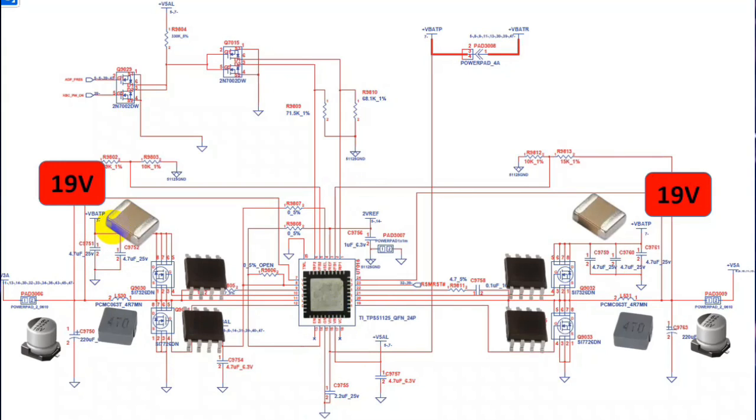Okay, so the same working principle here. So always the components that you should check when you have a failed 3 volt 5 volt circuit are the IC, the MOSFETs in both channels, the ceramic capacitors and electrolytic capacitors.